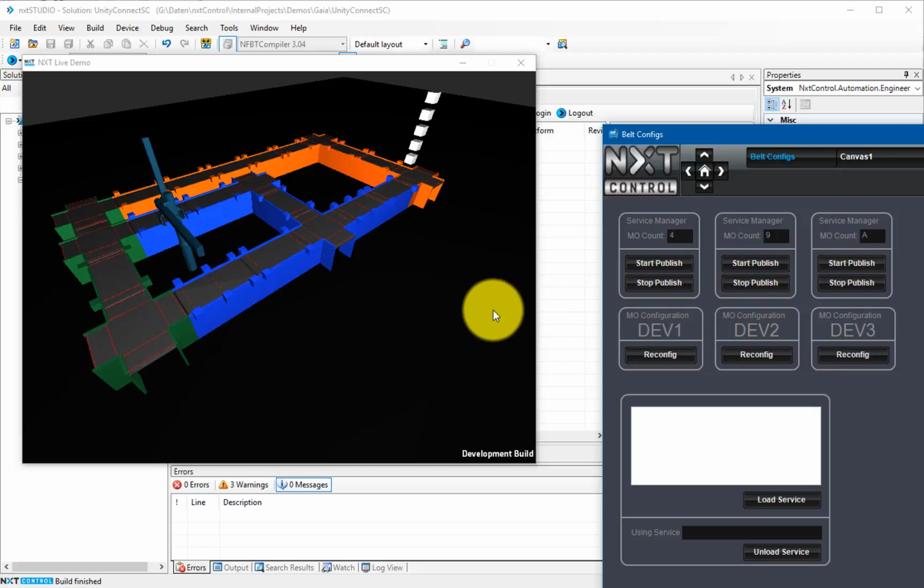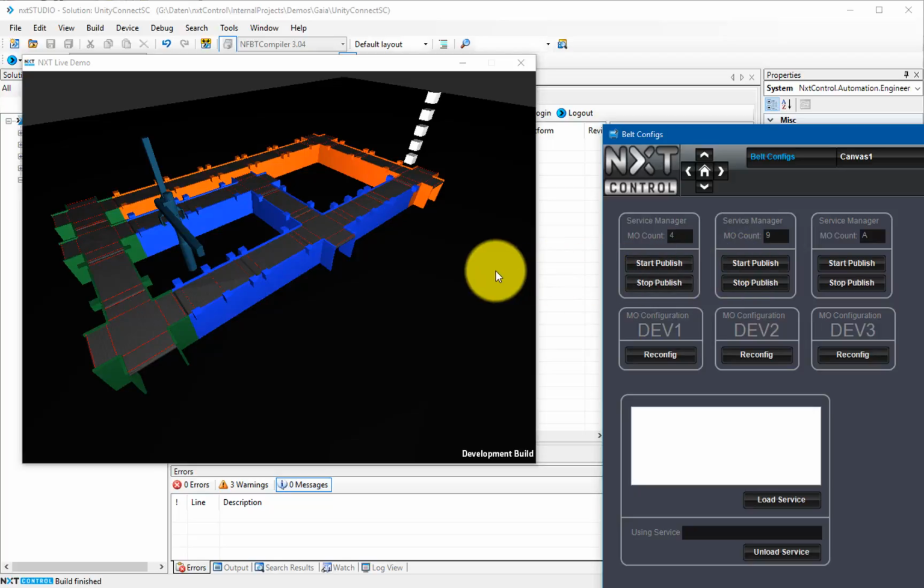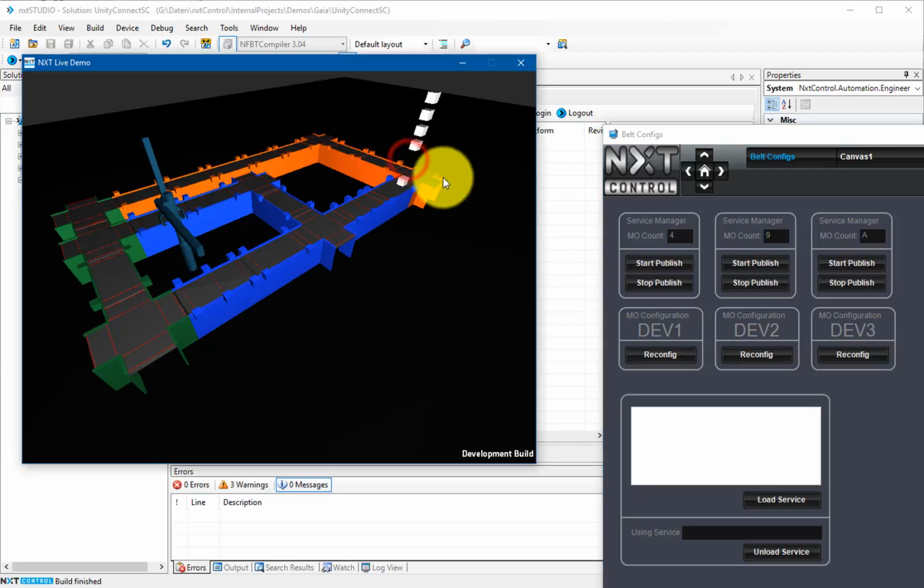The Unity model is completely controlled by the automation controllers. The control logic for starting and stopping of belt drives is located in the controllers. The Unity environment is used to detect collisions of the simulated objects. In our example, we have light barriers as part of the conveyor. When we put objects in the model onto the conveyor, light barriers get detected and the information is forwarded to the controller. The program controls the belts and avoids collisions of parts on the belts itself.